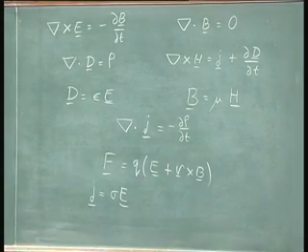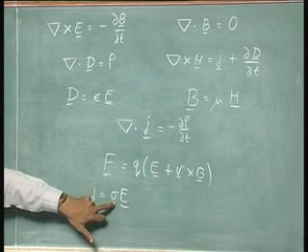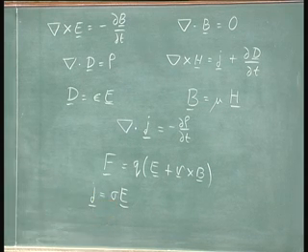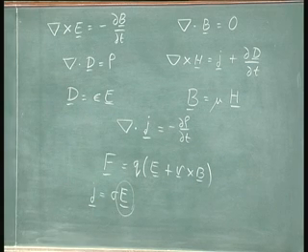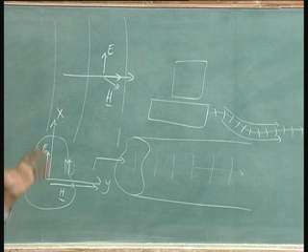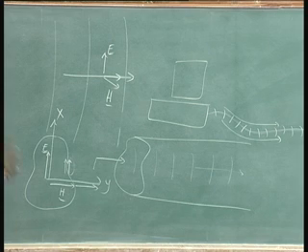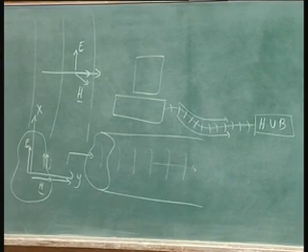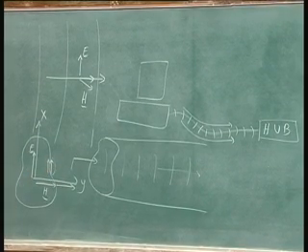So, if your conductivity, if your sigma is extremely high, you cannot really afford to have a large electric field, which means that this kind of solution is not possible. If you try to package what is called a plane wave, the kind of wave we have been looking at, and put it into a pipe, the plane wave will be destroyed in centimeters. It will just not survive.